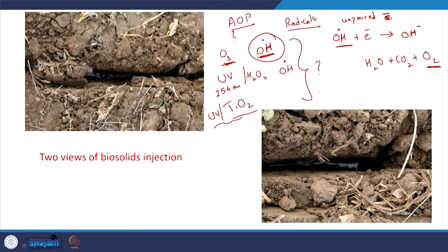So, one last aspect to note, after we looked at the relevant costs, as when we just looked at the dose and such, is that you will have to be concerned about scavengers. As in, whenever I have the hydroxyl radical, it will either react with my target which I want to happen, or also react with my scavenger which I do not want to happen. But hydroxyl radical is not selective, it will react with whatever is out there. So, I have to be concerned with these parallel reactions and such, right. Okay. So, with that I am done with the technical information.